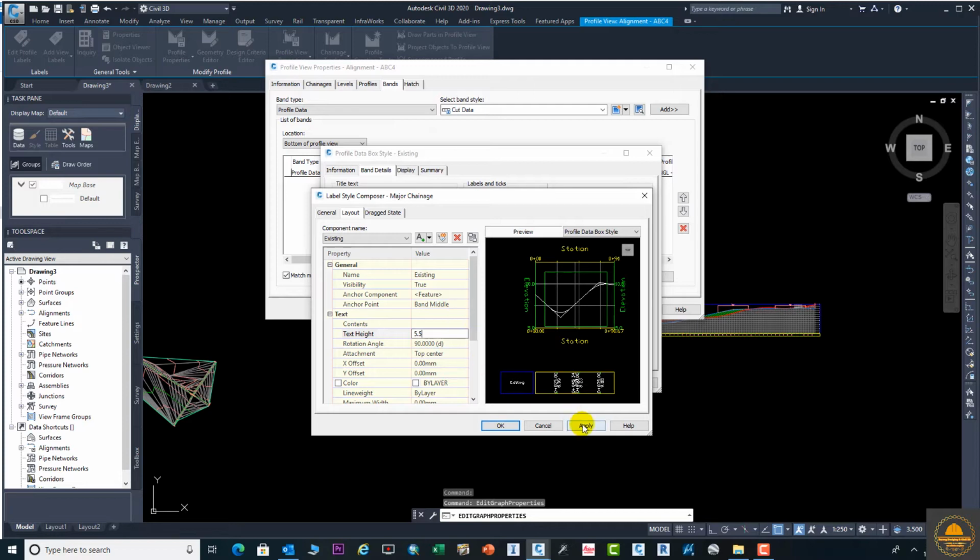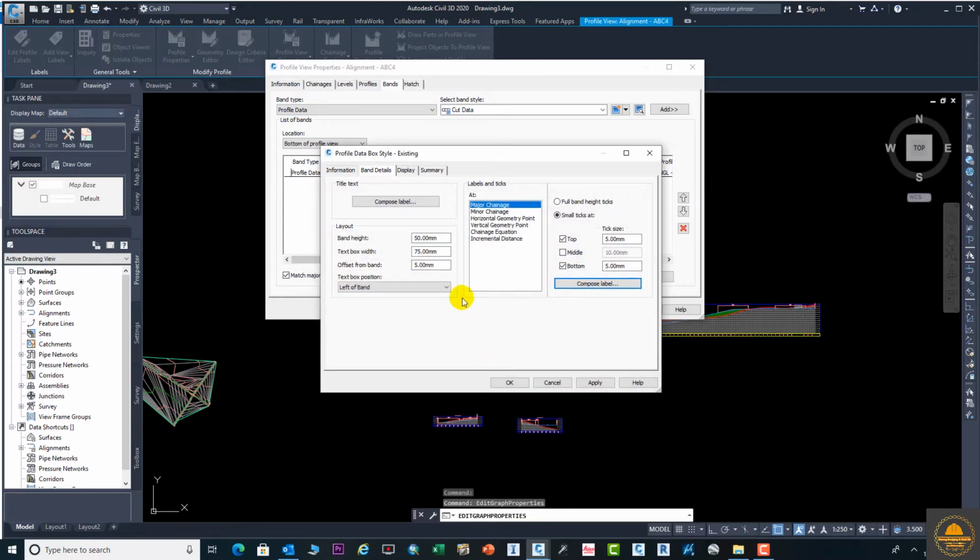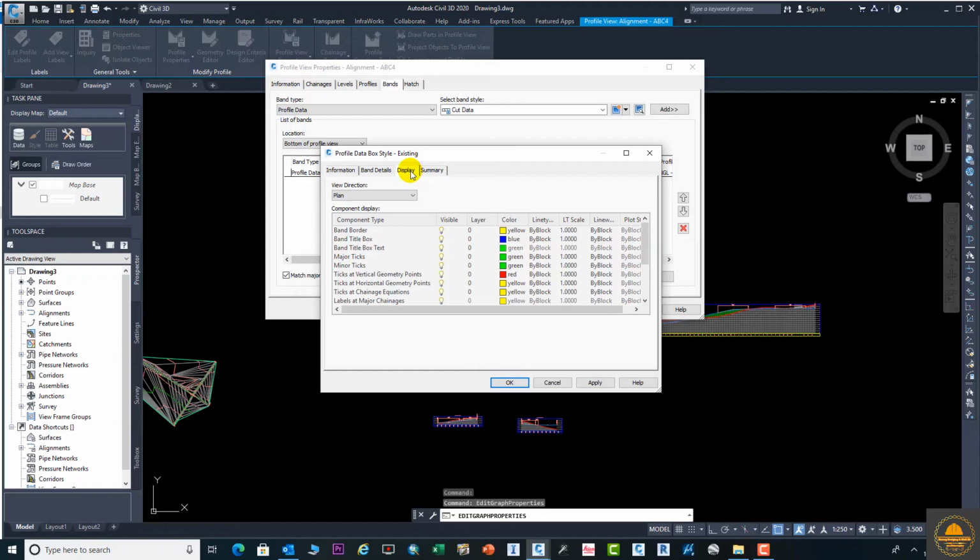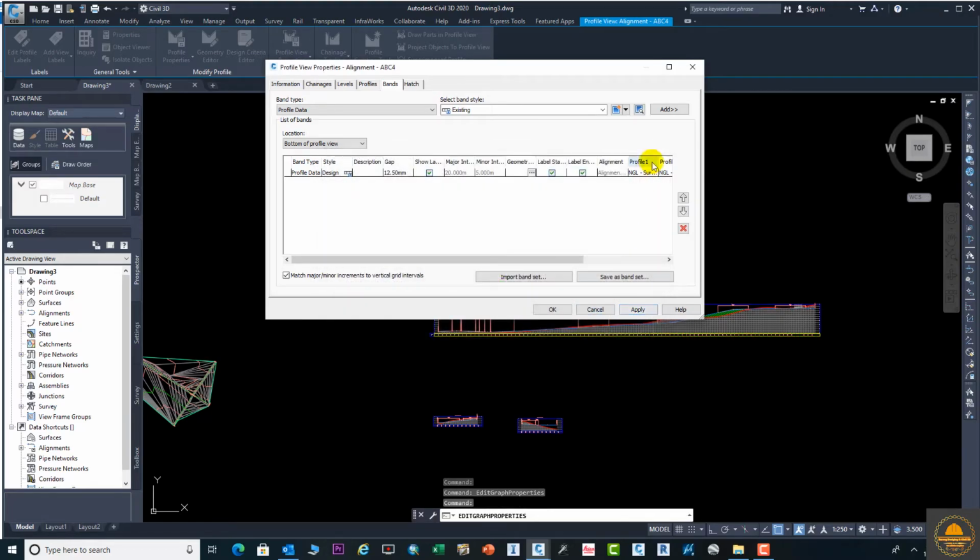Now we need to go to the display, in the same procedure, and turn off these unnecessary layers. Five layers remain; we need to keep open the first 4 and this one labeled major change. And now we need to do the same procedure, add and okay. So from here you need to apply and okay.